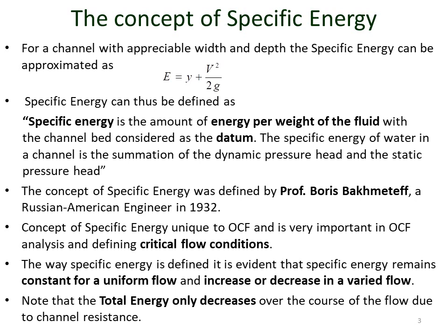So the specific energy can be defined as the following. I will read out the definition. Specific energy is the amount of energy per unit weight of the fluid, with the channel bed considered as the datum. The specific energy of water in a channel is the summation of the dynamic pressure head and the static pressure head.